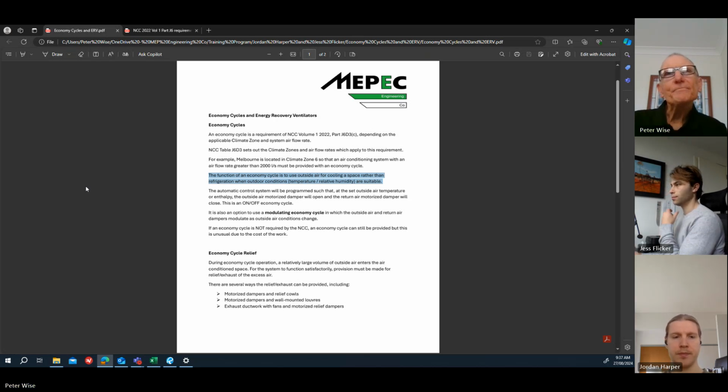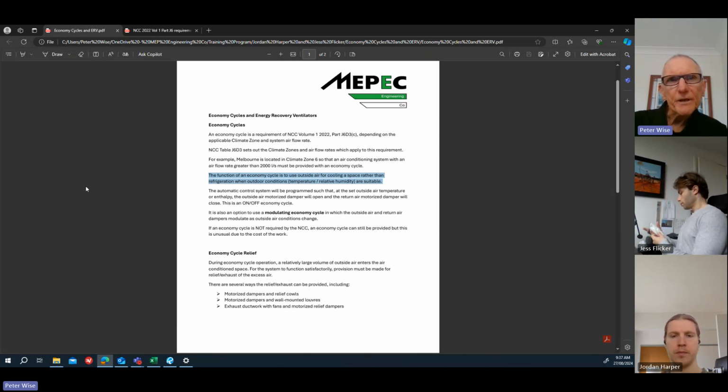So in your air conditioning system, you've got a supply air duct, you've got a return air duct, and you've got an outside air duct, okay? So in the return air duct and outside air duct, you have motorised dampers if you're going to have an economy cycle. And when you're changing over to economy cycle, the return air damper will close, the outside air damper will open, and you'll be using outside air for cooling rather than the air conditioning refrigeration system, or if it's a chilled water system, rather than using chilled water.